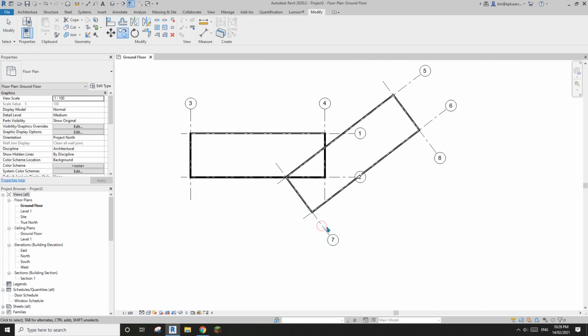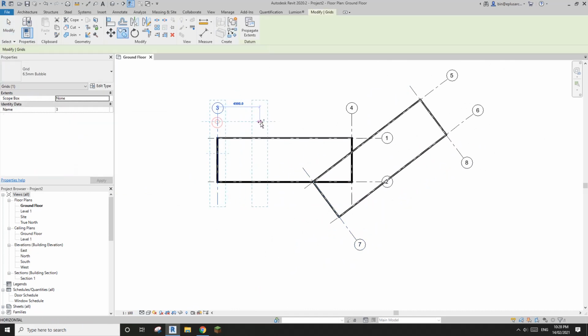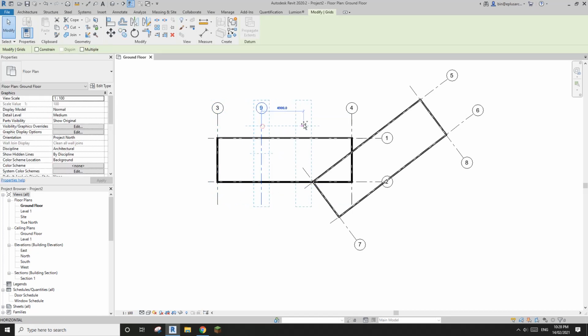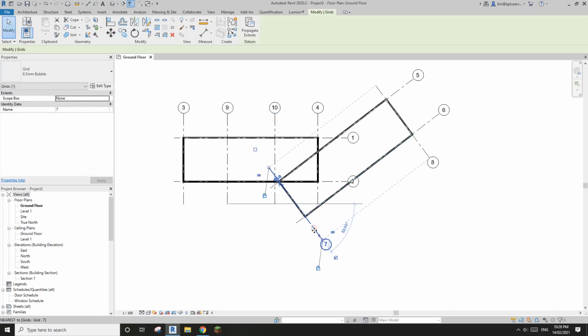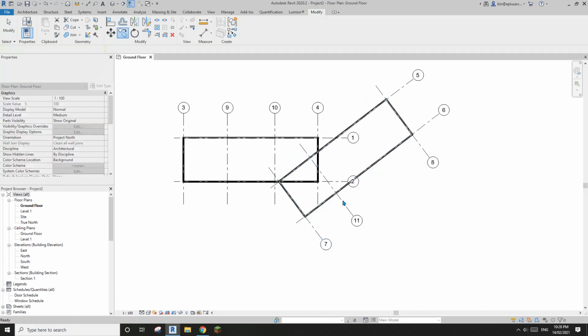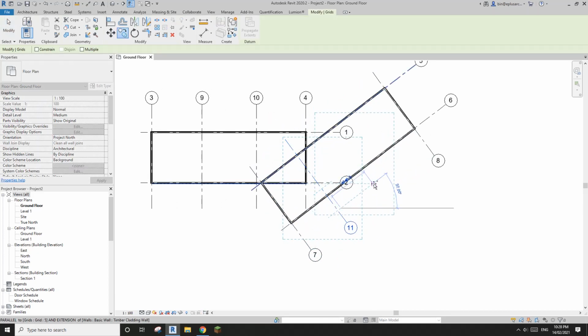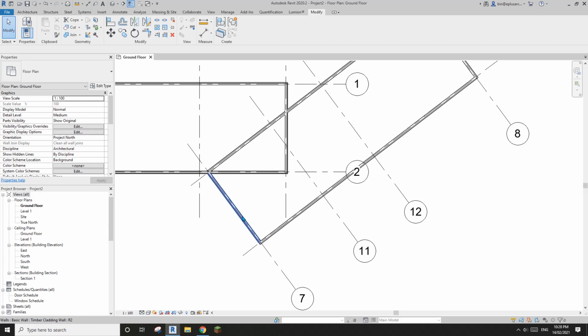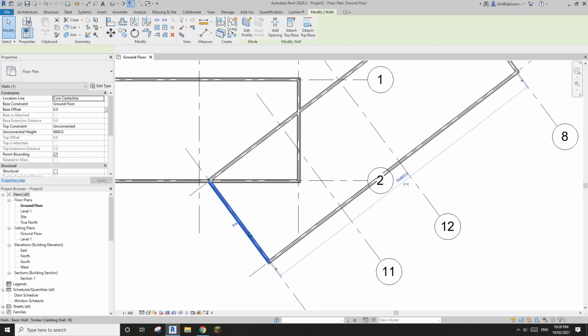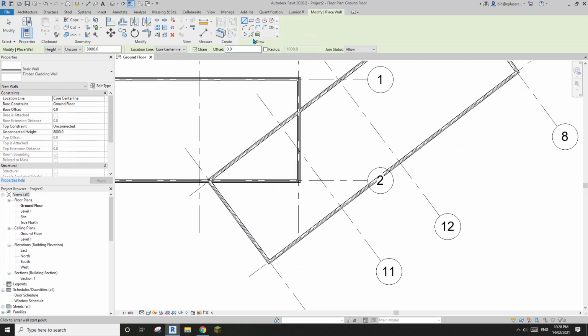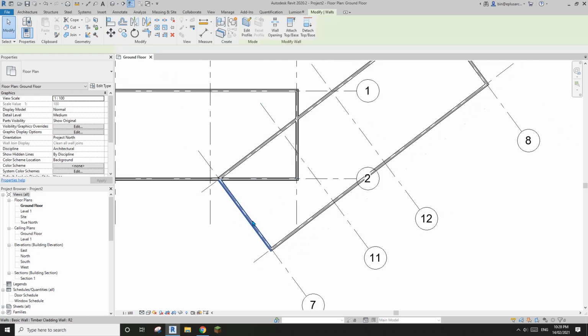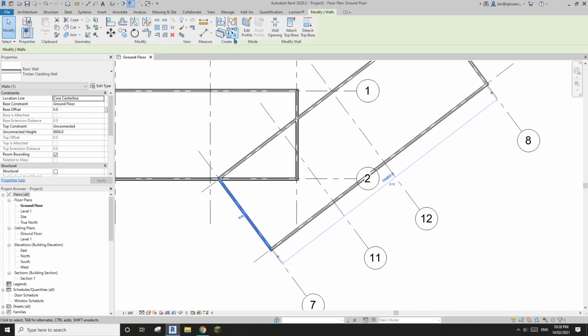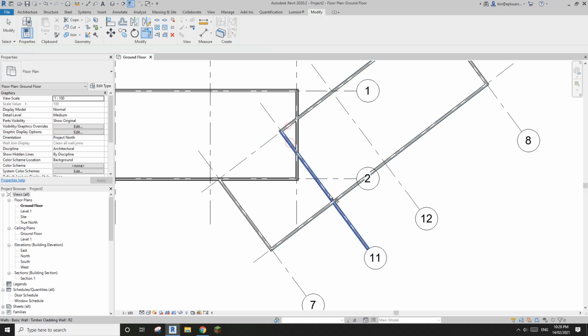I'm going to just roughly place more grids. Let's pretend these grids are for some internal walls or structures, and I'll just copy them and place them. Maybe like this. Okay, so now I'll place another wall here. I'll select this wall, CS, create similar, or you can also use this one here. So CS, okay, and pick, and also pick line, and pick this wall, trim it.